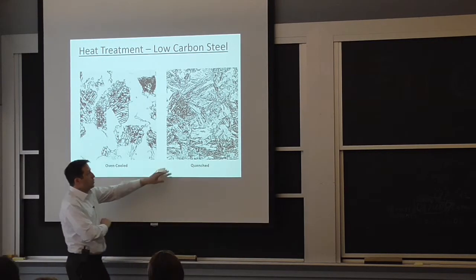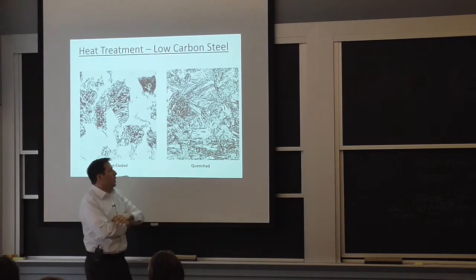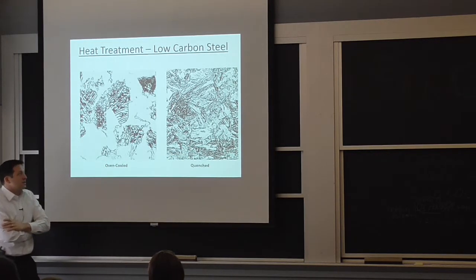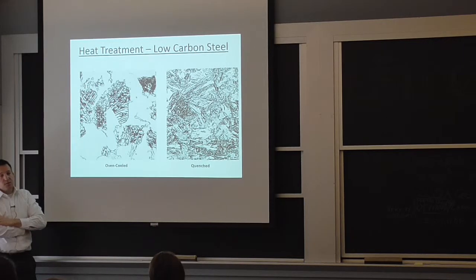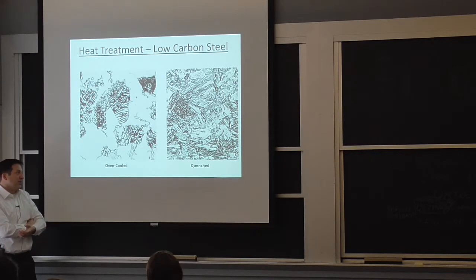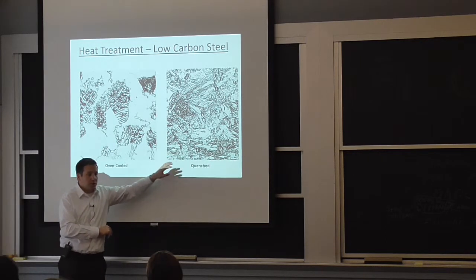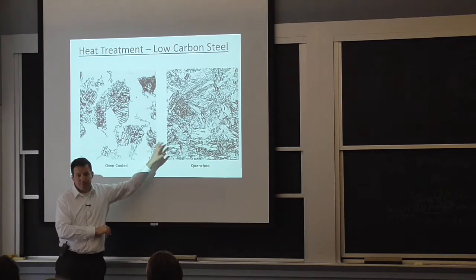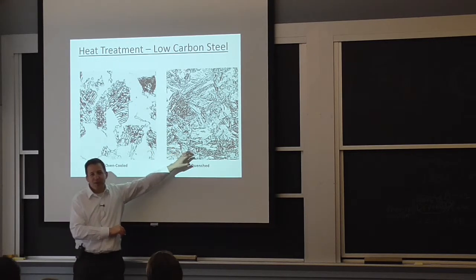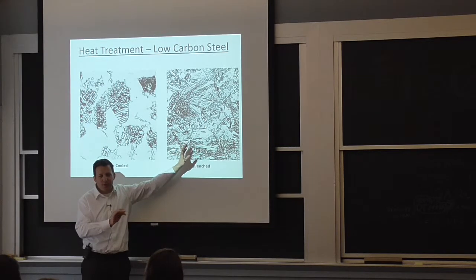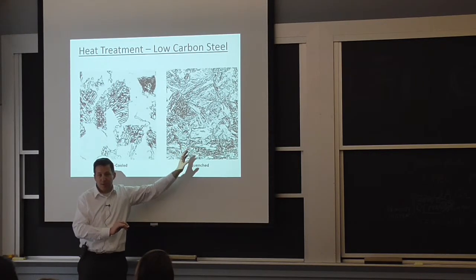If you go to this quench microstructure, most of the time what it is, you get the steel really hot, red color, and you quench it in oil, water, or media very quickly. And if you cool fast enough, or you have the right alloying element, you'll form this microstructure that's just completely different, right? This and this. Over here, deformation, just take my word for now, deformation is very difficult.